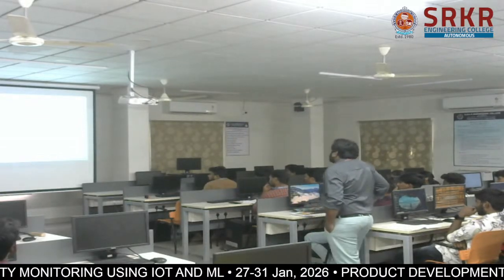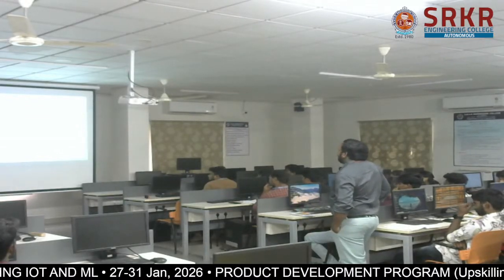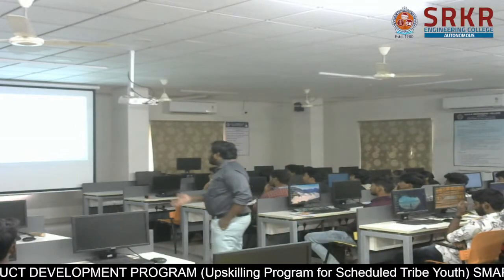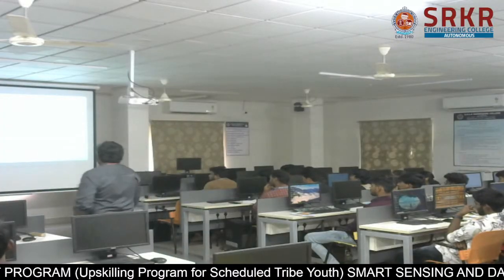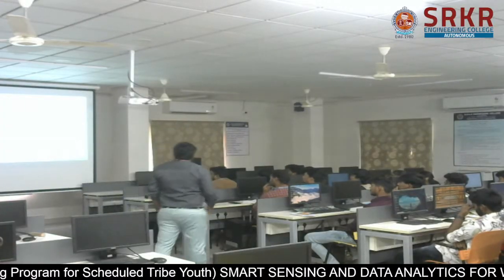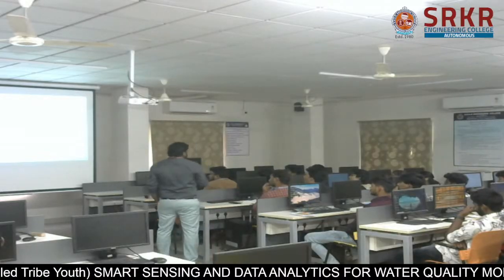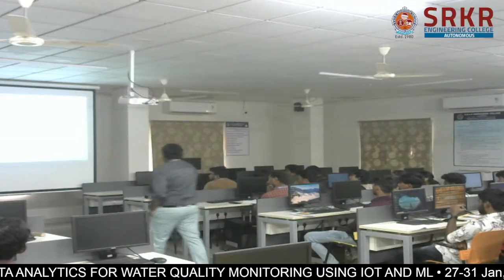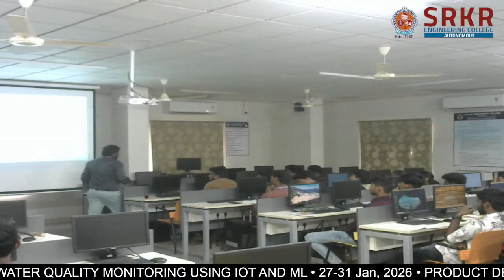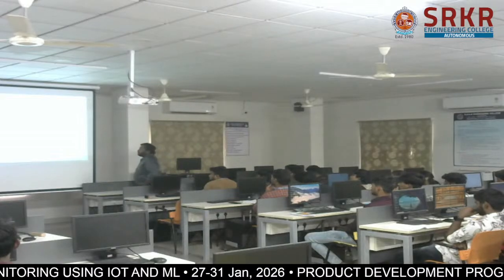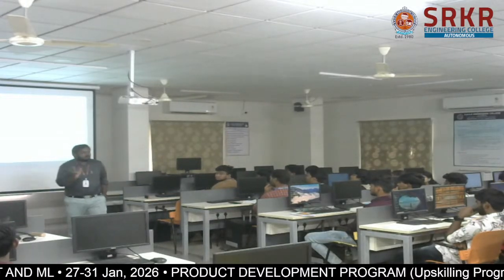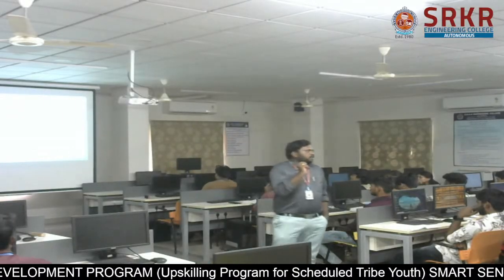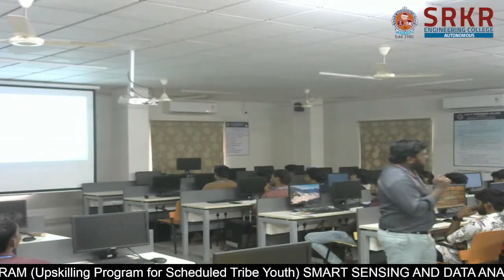In the data collection here, we have vibration and then temperature, because it is a mechanical related thing. If temperature increases, generally the vibration also increases. So at 5 time intervals, we recorded the data of both vibration as well as temperature. This is the data recorded from the sensors directly. Now see the processing. The individual vibrations may not be helpful to take the decision.